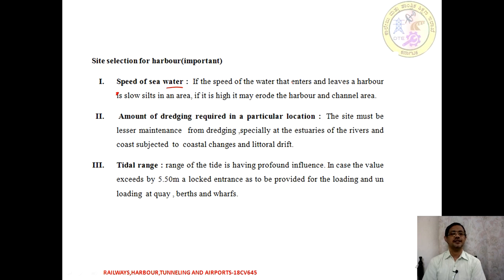Next is going to be the tidal range. The range of tide has a significant effect or influence. In case this tidal range value exceeds 5.5 meters, a locked entrance has to be provided, it means you should provide a locked entrance for the loading and unloading activities at quay, berth and wharf. So, that is the importance of tidal range, it is selected with respect to the facilities to be provided.